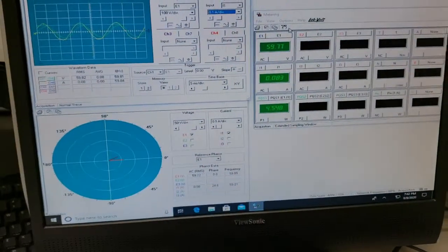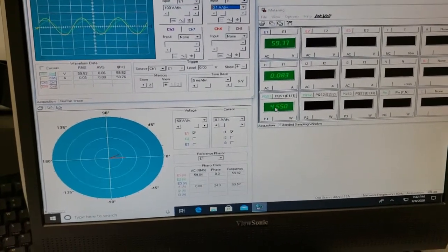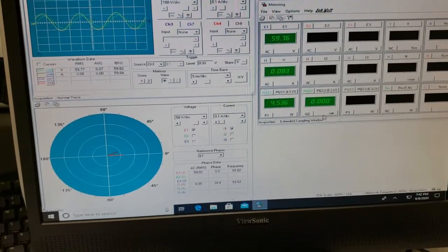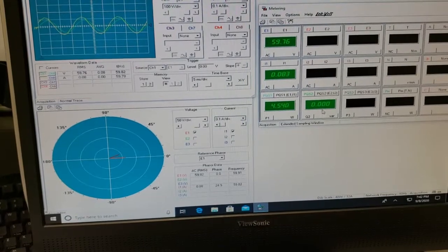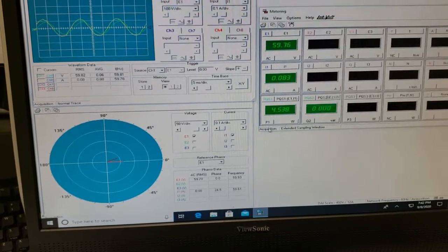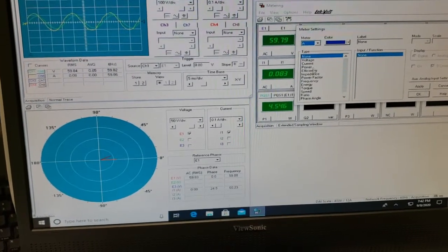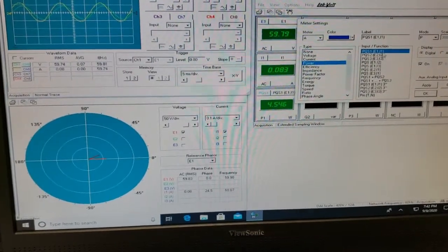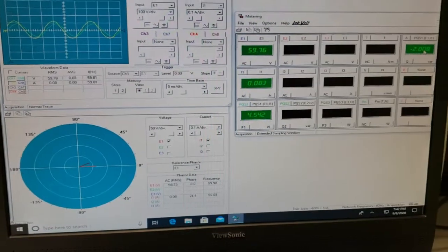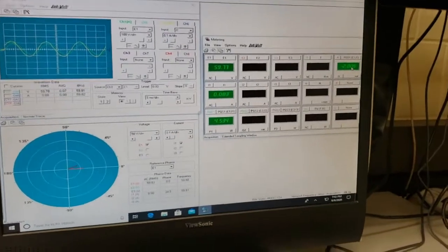You can see for this more complicated load, we have about 83 milliamp being drawn, about 4.5 watts of real power. And let me actually do something real quick. I did not put this in the lab to do, but I'm gonna do it anyways. Oh, it's E2I2. Yeah, let's change this real quick. Never mind. Here we go. I'm just gonna show that it's drawing reactive power as well. Okay, so I1 Q. There we go. So it's drawing about -2 VARs of reactive power, which means that it's a net capacitive load, by the way.